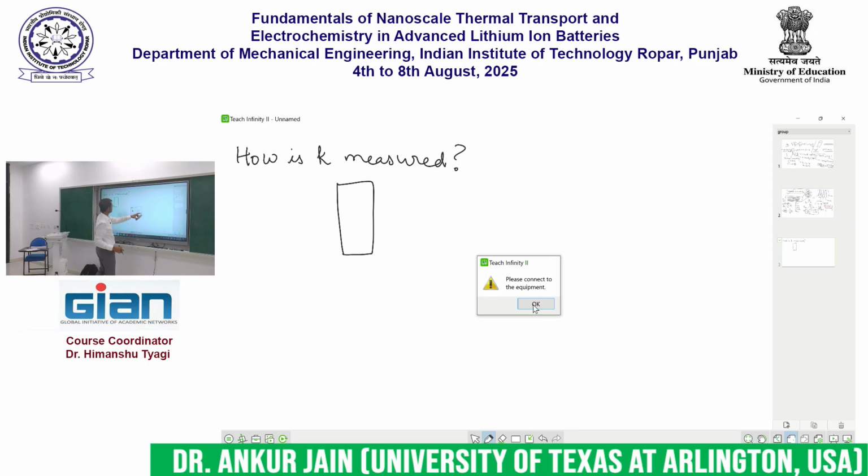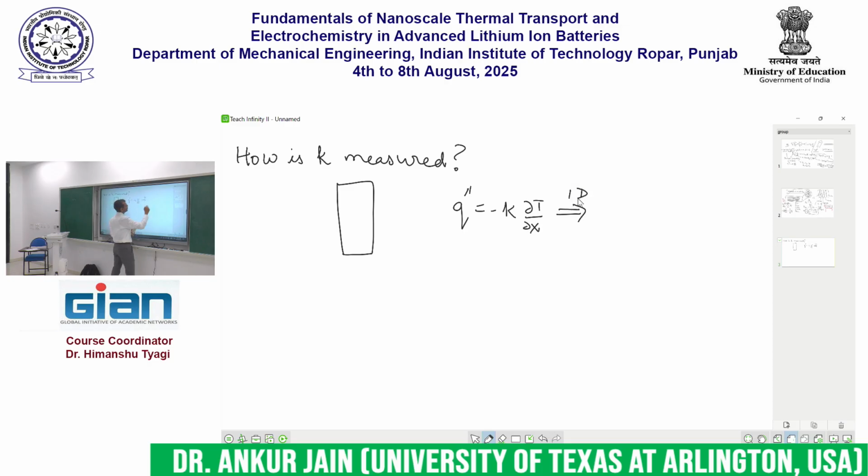Well, the thermal conductivity is governed by the fundamental equation q double prime equals negative k dT/dx, which in a one-dimensional problem could be simplified to Q equals negative k A delta T over L. In other words, if the cross-section area is A, the thickness is L, and there is a temperature difference delta T across, and that causes Q amount of heat to flow, then k is simply given by QL over A times (T1 minus T2).